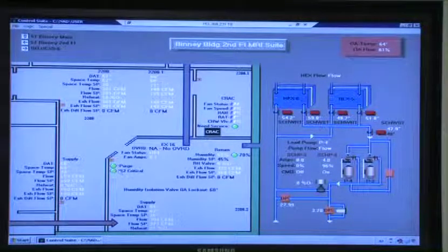Yeah, to the operation center. This purge system, is there a purge button? There's a manual switch on the wall. So somebody in that room can actually activate it by turning the switch. Now, if the O2 goes off, will they both go off, or will only this go off? The O2 and the purge are two separate points. If it trips based on oxygen depletion, that will go red. If somebody turns the hand switch, then the purge will go red. So depending on if it's an automated process through the meter, that starts this purge exhaust system.